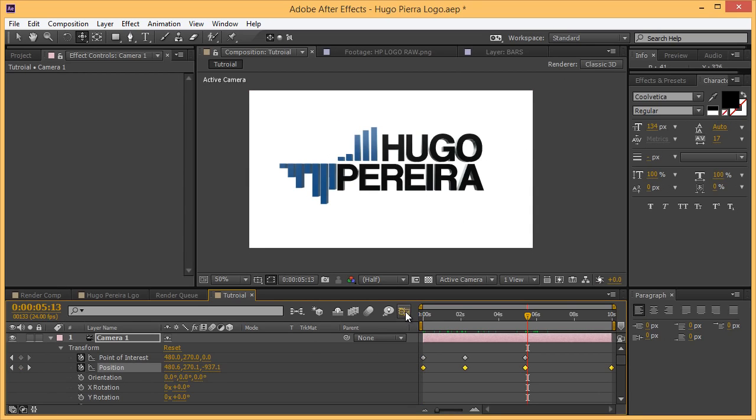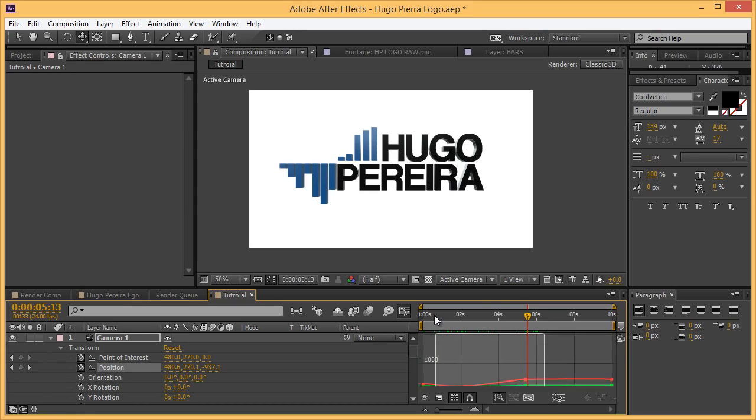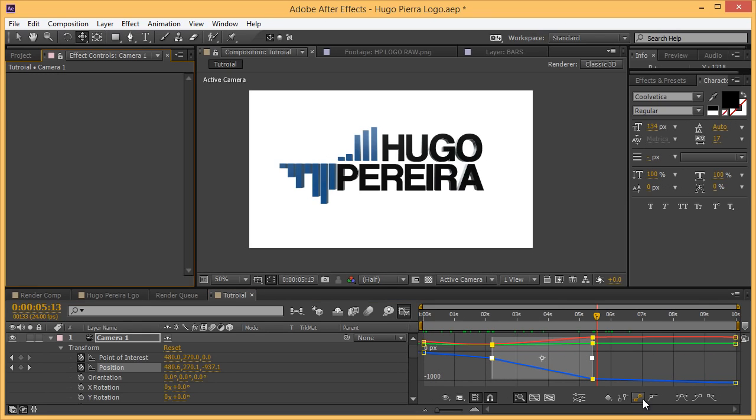If we come over to the waveform edit tool, you can see it creates some weird points and some interesting curves. But if you select all your keyframes in the waveform editor and hit the Auto Bezier, it should smooth them out pretty nicely. That's actually a better solution than just hitting F9 on the keyframe, which is what's called Easy Ease.